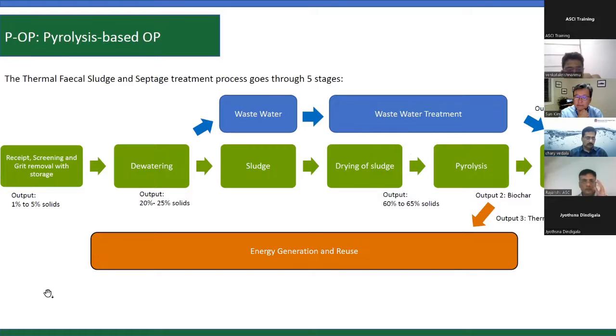And this is also a very climate resilient solution. You don't have sludge sitting in a drying bed for a couple of weeks before it can be somewhat safe to handle and give away to farmers. We are in a region where there is lots of rain and a lot of flooding, maybe an outcome of climate change. Having such a system means the treatment happens on the day the septage is received. So you don't have the problem of this overflowing into the cities and water bodies, with germs getting carried away along with the fecal matter. So this is very climate resilient.